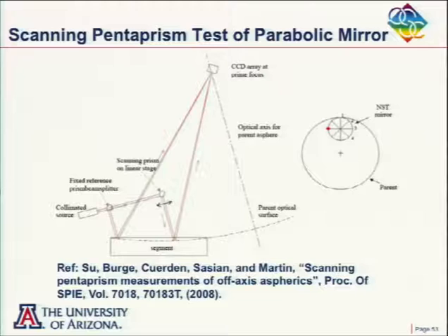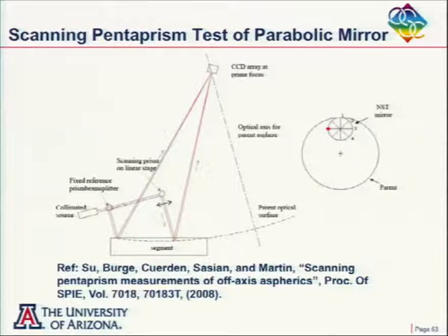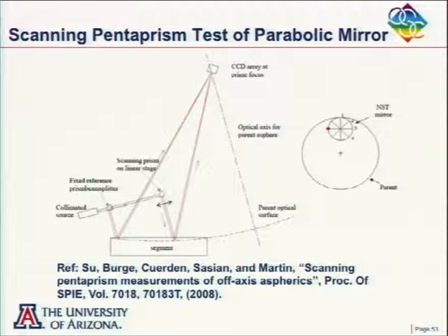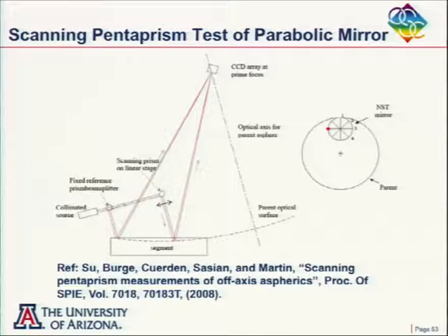When you use it to test a flat, you can use the reflection coming back through the prism back to an autocollimator, and the reference prism will be one angle, and then you measure relative to that. And you can do a rotation where the reference prism will always be at the edge, and then you do scans at different clockings to see what the angles of different parts of a flat mirror are. And it's always returning back through.